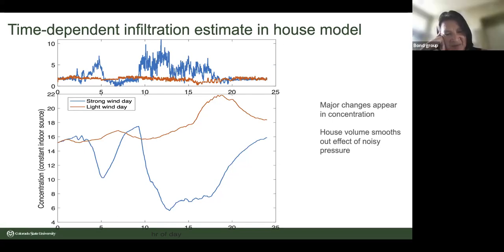And so you need to know the wind average. I've been measuring the 2 taps on the same wall, and they can be quite different when it's windy. And so then I started wondering, like, how representative is each tap? And I think you just mostly need an average over that period. These are 1 minute data, by the way. And so the measured pressures are real, but the concentrations are inferred from the model.